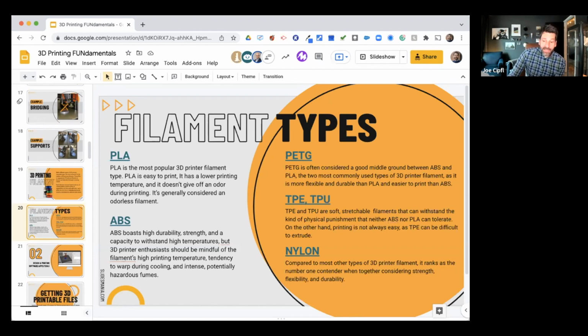Okay, ABS is the most well-known plastic on earth. It is what almost everything that's made out of plastic is. All of the plastic stuff that's in front of you right now, this second, is ABS plastic. ABS plastic is used for injection molded plastic. It's very strong. However, when you're printing with it, it gives off VOCs and fumes, so not for classroom use. You would need a vent hood if you were maybe in a science lab. If you are a CTE teacher and you're working in a shop, certainly a ventilated shop is going to be fine.